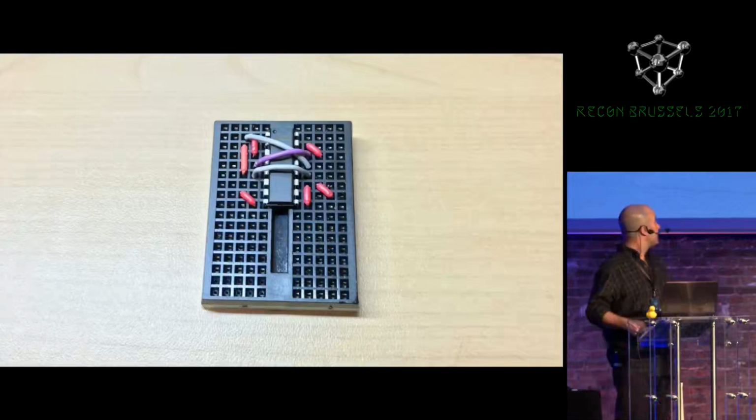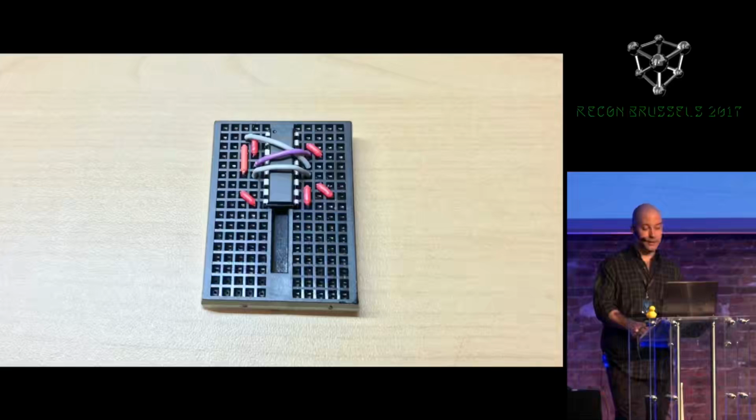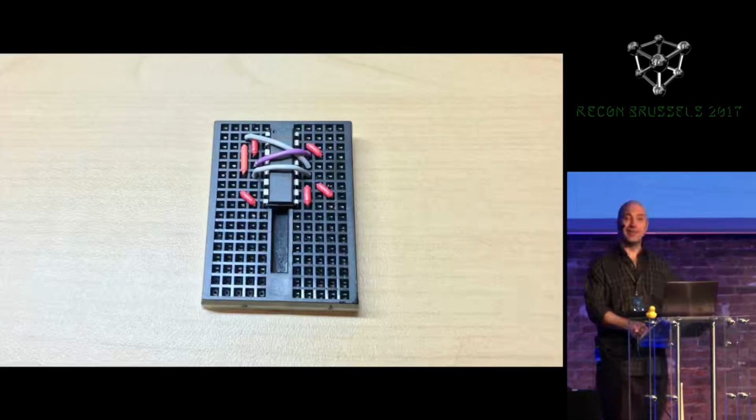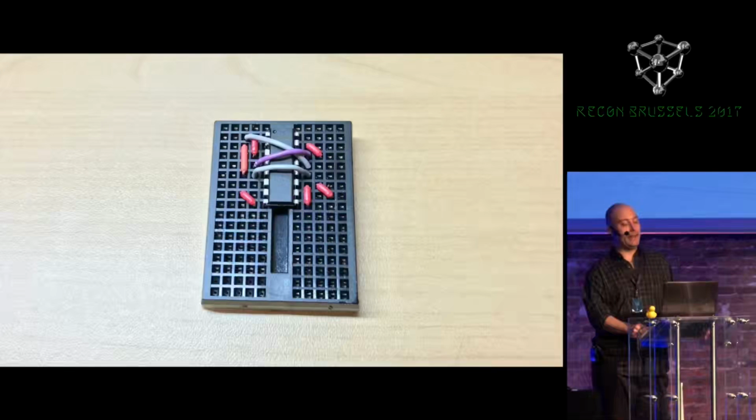So this is the actual circuit with the MAX 4619. This is basically the whole glitcher board, minus the XMega that I use as a microcontroller. I like the solderless breadboards. They're very convenient to work on. They allow you to change your ideas very quickly and test different things out. Any problems with high frequency noise or anything like that, really for most of the projects that I do, I don't notice too much of a problem with it. I'm able to ignore it and kind of do things the cheap and easy way. So I enjoy that I'm able to just pop a chip into the breadboard, connect these wires, and in a few minutes I've built a glitcher like this.